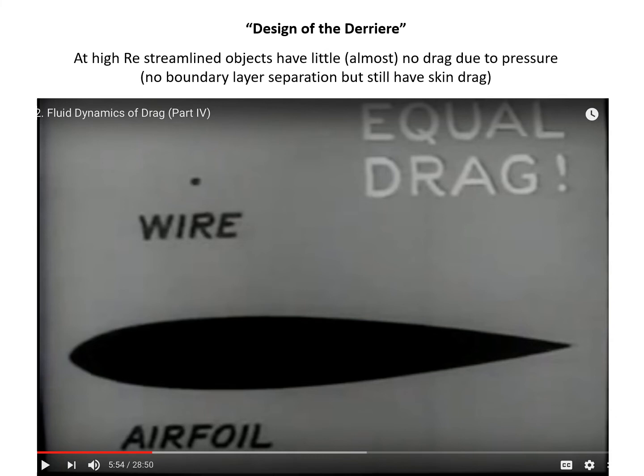So at high Reynolds numbers, these streamlined objects have almost no pressure drag. They recover almost all of that pressure momentum, and Newton's equation of motion is made up almost entirely of the inertial forces that are equal to this skin drag.